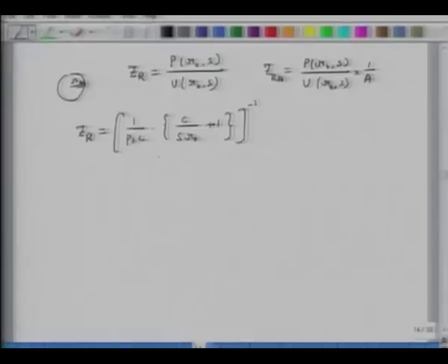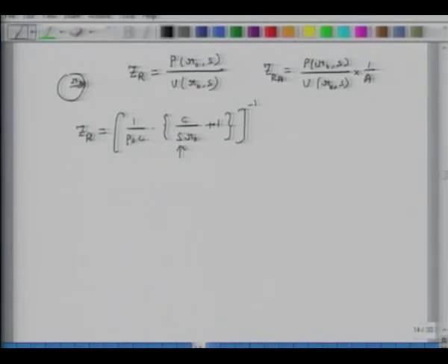You see here that there is an S component, which means that the impedance offered by a pulsating sphere is not purely resistive. So whenever you have a pulsating sphere, it will, by nature of its presence, introduce a non-zero psi in the entire circuit, which means that at the amplifier level, it will draw more than the optimal value of current, and it will require more than the optimal value of voltage.